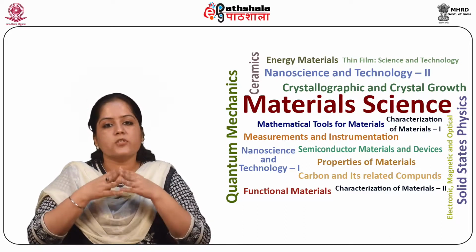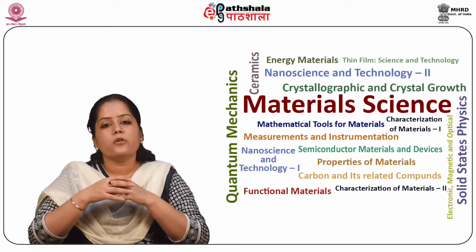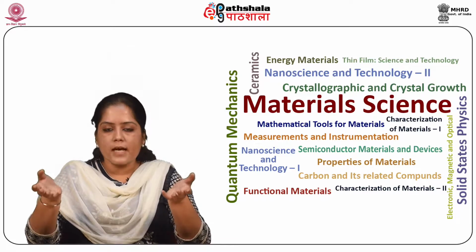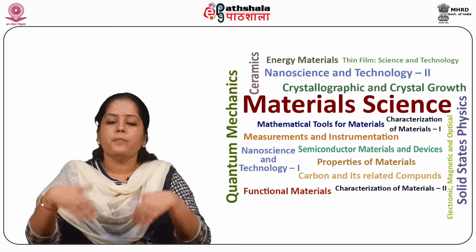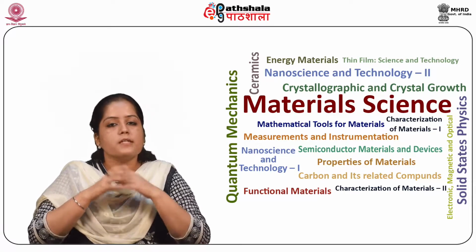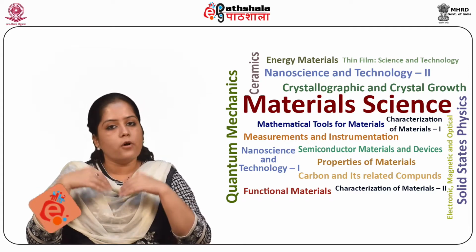An example of stress-induced phase transformation is transformation toughening in zirconia and other ceramics. Both the stress-induced transformation and microcracking lead to a very significant increase in the fracture toughness. Now, crack bridging. It is often observed in large grain-sized ceramics. Some large grains bridge the two crack surfaces behind the crack tip. More than one grain may form frictional interlocking bridges across the two crack surfaces. These bridges take up part of the load on the crack tip and thus reduce the effective stress intensity at the crack tip. The measured toughness is therefore increased.